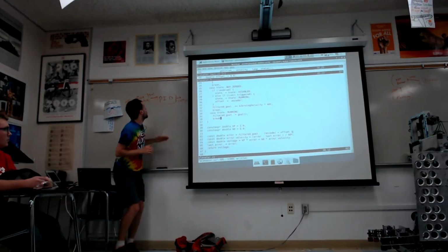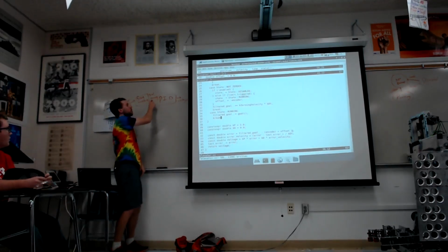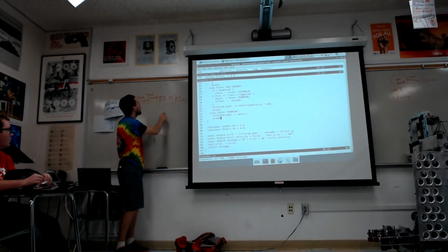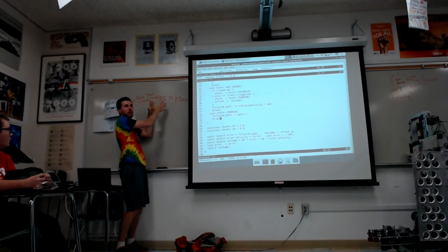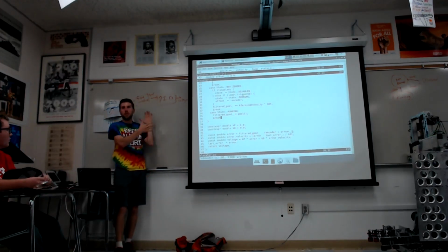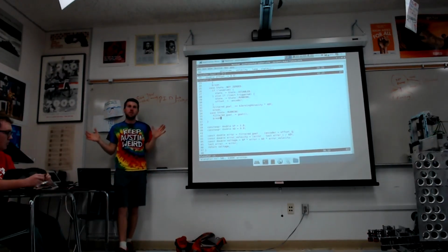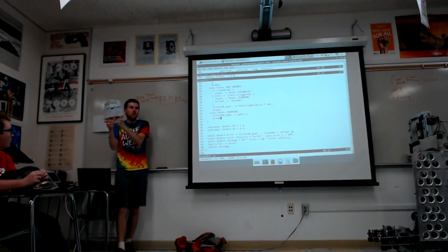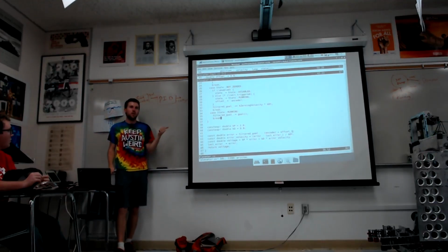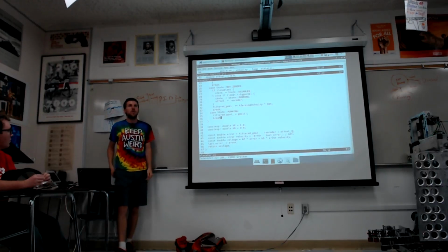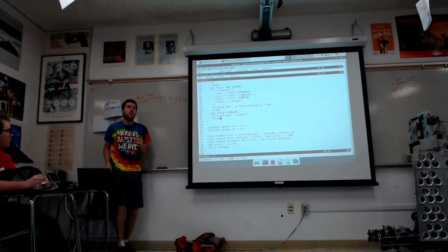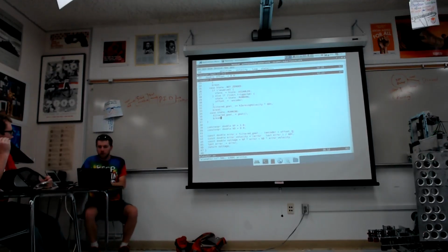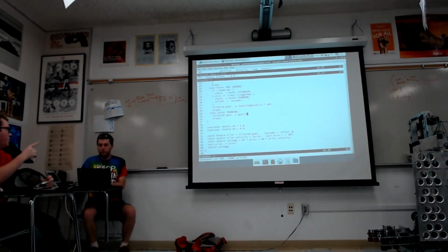Yeah, because what we want to do is, from our picture here, this goal should be in meters. This should be in nice, real, absolute coordinates. And then we want to have as much of our software working in nice, reasonable, sanitized, cleaned up units as possible, and isolate the little weirdnesses of our encoder to as small a corner as possible. So I'd like to put it down in the bottom for that reason. But yes, we could implement it that other way, and that would work fine. Yep.